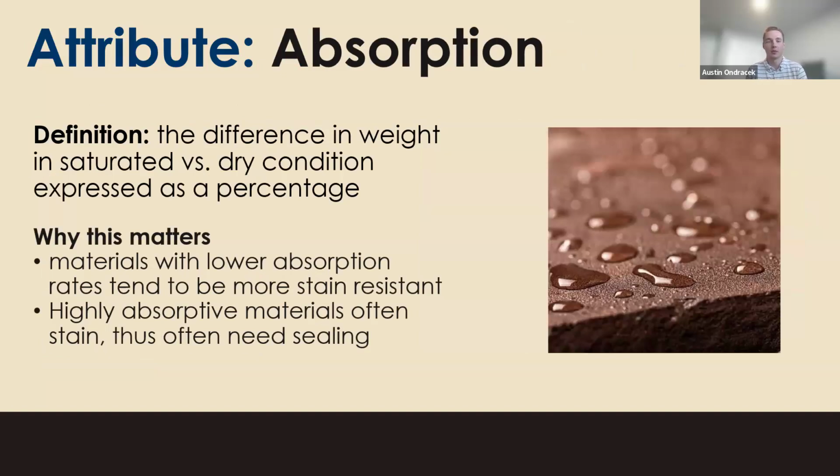Absorption, that's one big part of stone that it is super, super good on. For the most part, depending on what stone you spec, its porosity is so minimal and it is so dense that water cannot necessarily get into that stone to have that freeze thaw cycle to cause it to degrade. Whereas a lot more man-made materials that are precast aren't as dense, and it's a lot harder to prevent that, even with sealants, to keep that water from getting in, ultimately causing flaking and chipping over time. Natural stone inherently is built in to not be very porous.